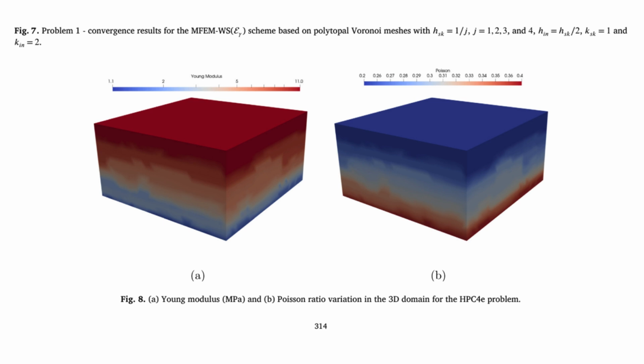And what are these primary variables that get solved globally? What takes up the main computational effort? The global system is dramatically smaller because it only includes the coarse scale primary variables. These are essentially two things. That traction variable we talked about living on the skeleton. The Lagrange multiplier connecting things. Exactly. And the other part is the rigid body motion components of the displacement within each polyhedron, basically how each block as a whole might translate or rotate.